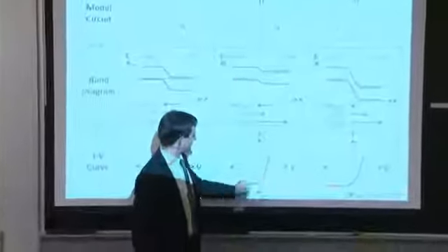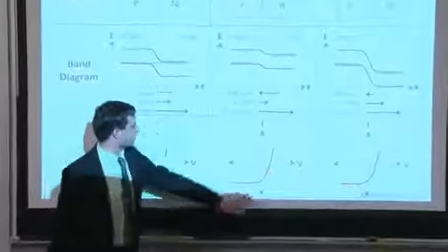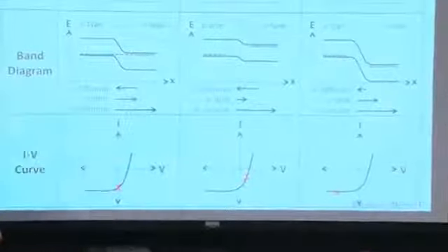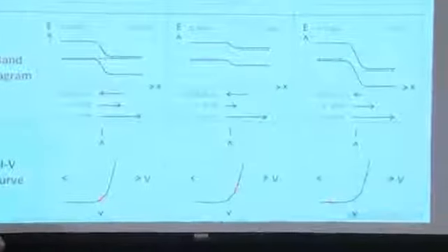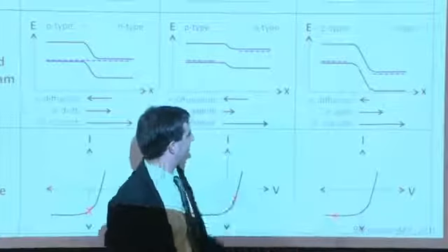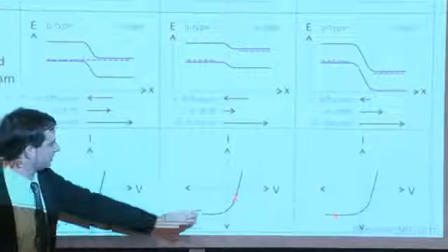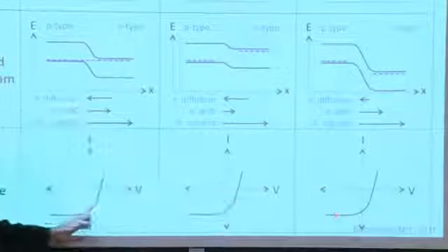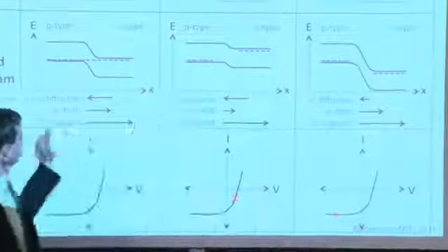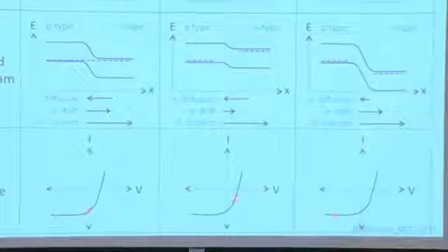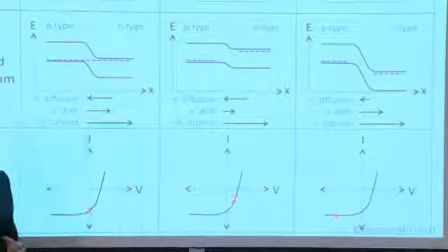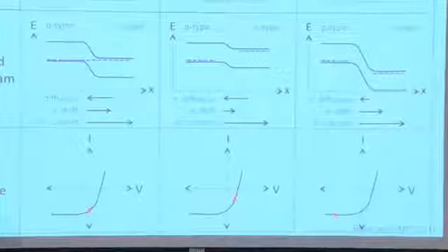We have our red X under forward bias conditions in the fourth quadrant, denoting that power would be flowing out of this solar cell device under these conditions. And now the bias is inverted. We have reverse bias conditions. And notice that the current has the same sign. So the current is negative here, and negative here. So the net current is always flowing in the same direction in all cases, because we have this illumination current, because we have this generation of carriers inside of the material.